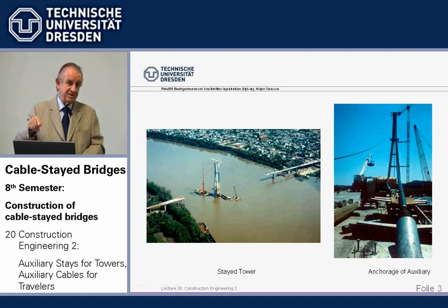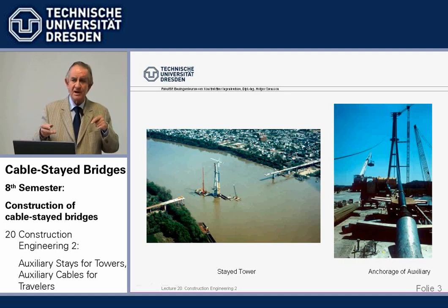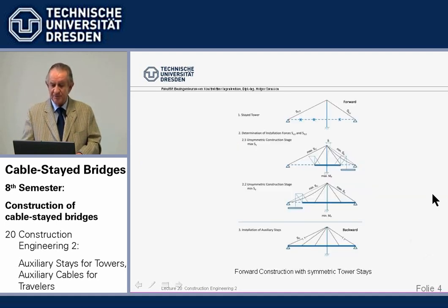During construction, we very often have to take into account the change of sag, the change of E modulus of the tower into effective E modulus, change of sag because the stresses change much more than in the final stage. You remember 7th semester, I told you effective modulus of elasticity, stress to the power of 3. Now that comes in here, but that's a minor point.